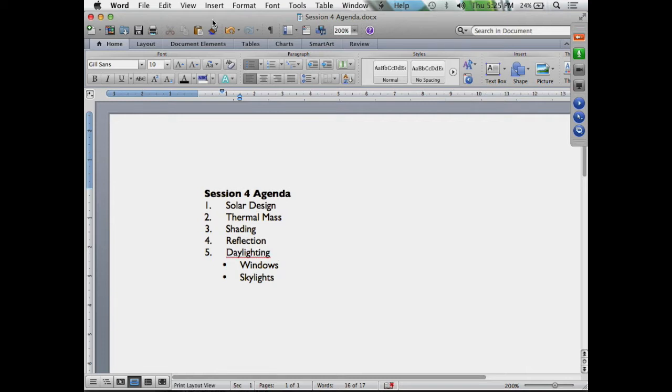Very thick, heavy materials like concrete are very slow to absorb energy, but at the same time, once they've absorbed that energy, they're very slow to re-radiate that energy back into the system. So they're actually quite good. You can almost think of them like little thermal batteries, where once they absorb that energy, they buffer the effect of anything happening from the outside world, but at the same time, they also maintain a relatively constant temperature and re-radiate at a relatively slow level. So they're really good dampers. They minimize and store all at the same time.